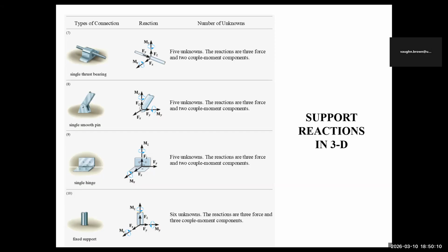between the Z and the X, but what will happen there is a shaft spinning. So in the Y, you'll only have a reaction, but no moment, right? So you'll get a moment in the X and a moment in the Z. Five unknowns. This one now is a spin in 3D.